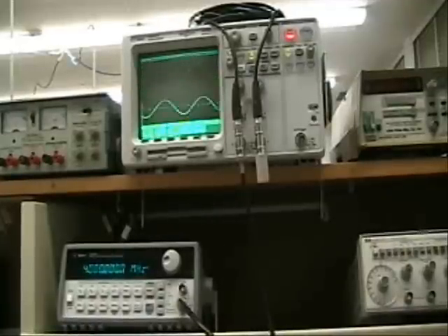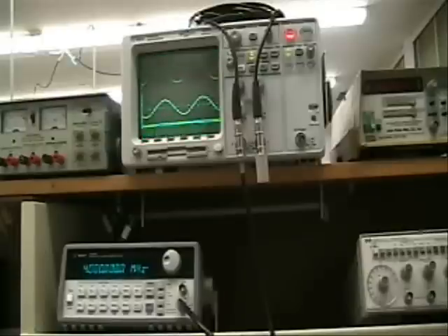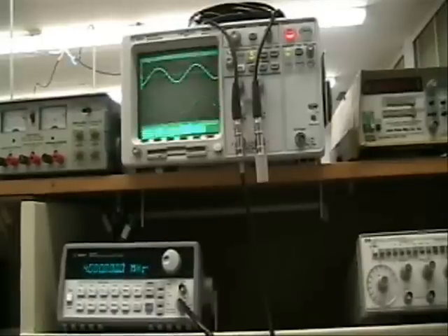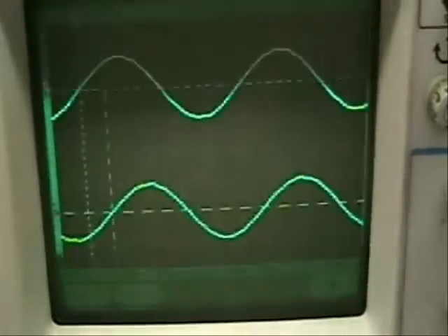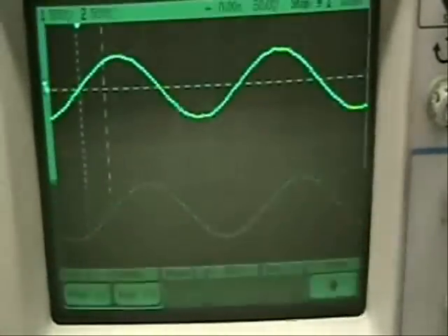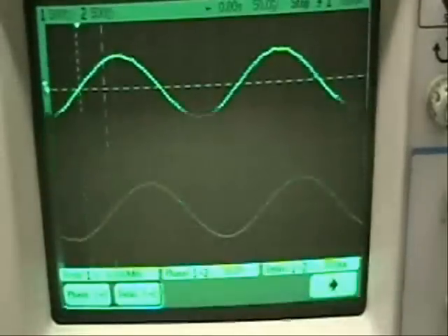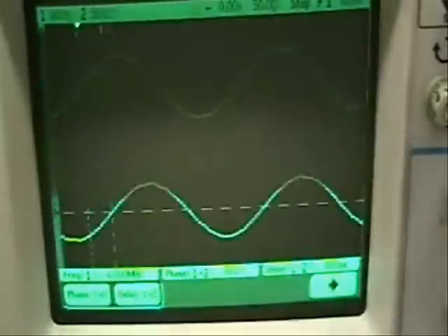Here is a short video of the lab operation. A 4 MHz sine wave travels down the transmission line, providing a signal at the beginning and end of the line. Scope measurements of frequency, time delay, channel 1 to 2, and phase shift, channel 1 to 2, are configured and averaging selected under the Acquire button. Recording the data to a table and downloading the screenshots to the computer complete the data collection for the laboratory.